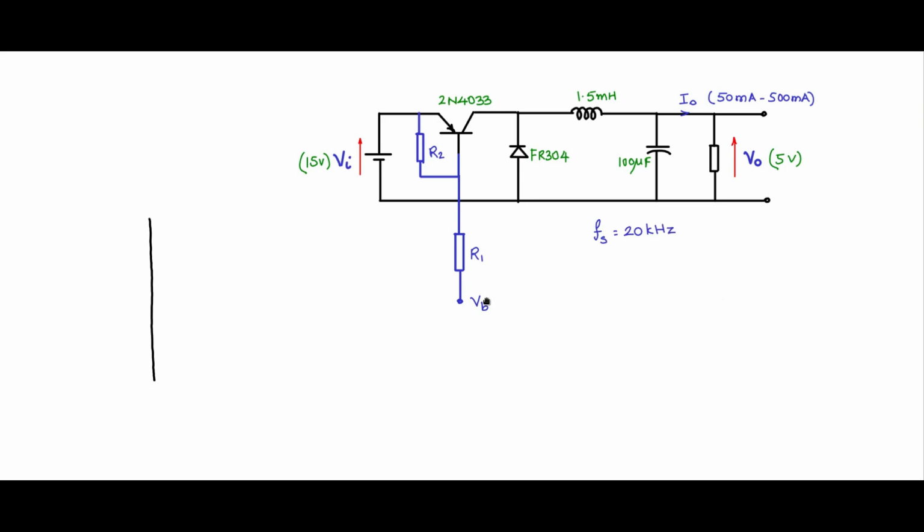So almost everything is ready except that we need to give the pulse width modulated waveform here at VB. We had looked at how to generate pulse width modulated waveform some time back, and I had also told you that there are commercial ICs available. One such IC is TL494, Texas Instruments TL494, very inexpensive, around 10 rupees or so. You should be able to buy that and use it. So let us make the connection for TL494.